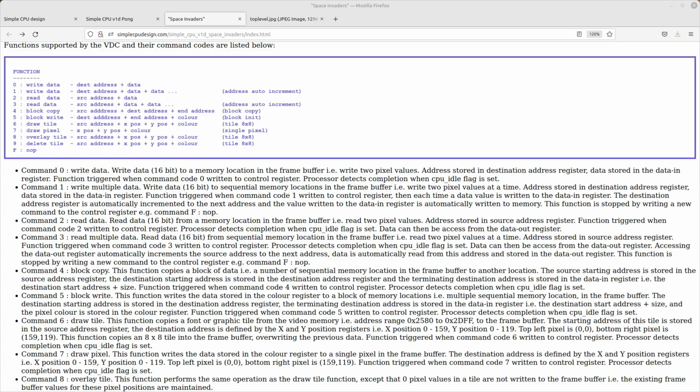However, these were implemented directly in hardware, so it was very easy to move these around the screen, as you could just give a movement command to the hardware. And commonly the hardware would also implement hitboxes, so the processor didn't have to determine if the two sprites were colliding. The hardware could perform those calculations for you automatically, so it offloaded quite a lot of processing into this dedicated hardware.